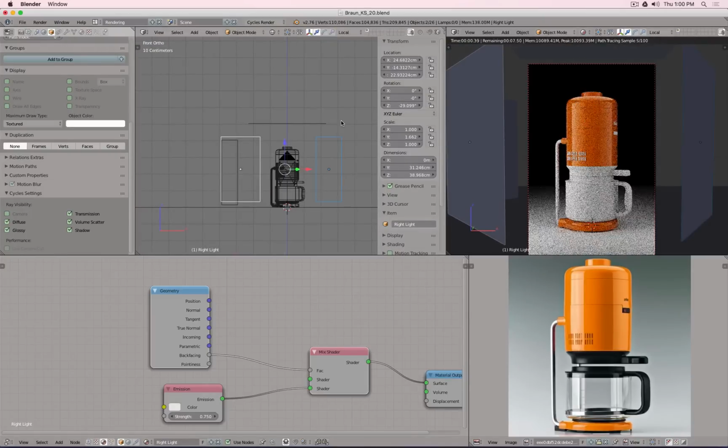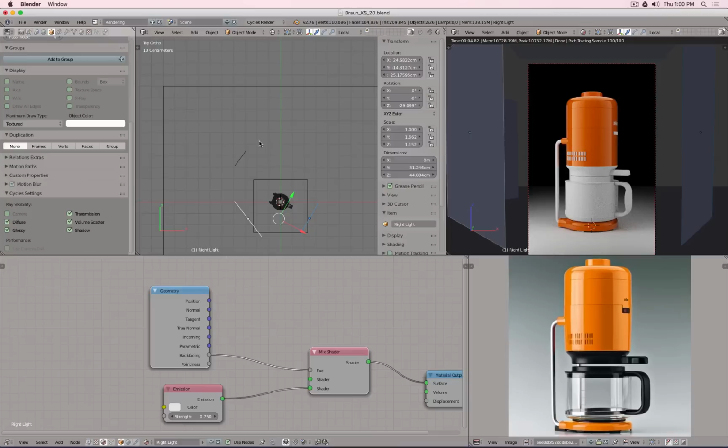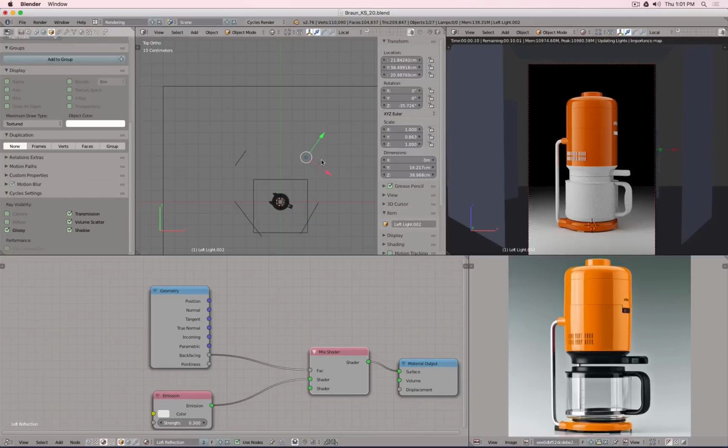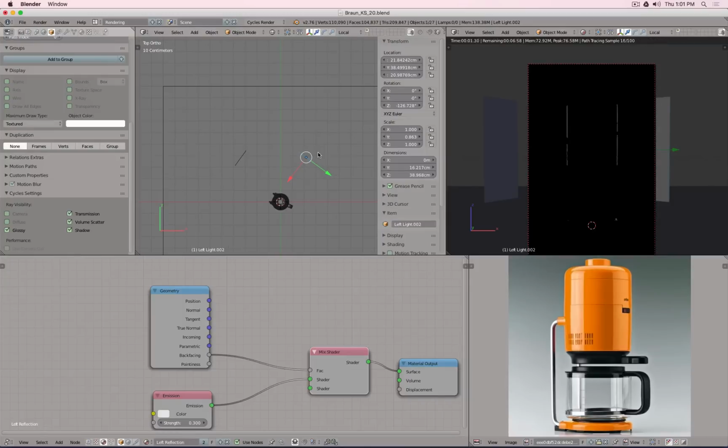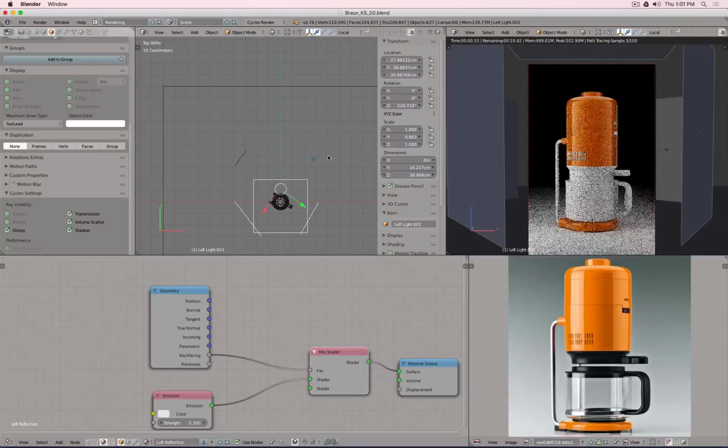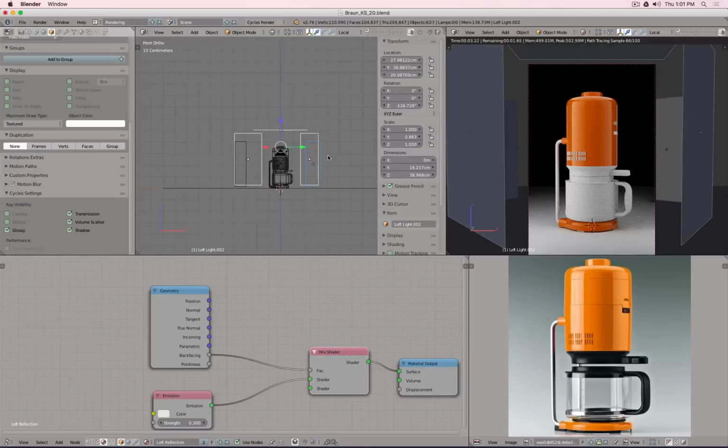Can actually move this one down and press Shift or S and then Z to scale only along the Z axis. Okay, maybe like this. There. Also here on the right side, I need the small reflection helper there. So we rotate this one. And again, to see this better, maybe I turn this one off. Whoops. Not hiding that one. G. There. Okay. Perfect. Good. So that wasn't too difficult.